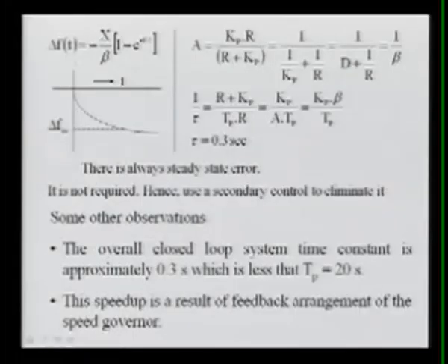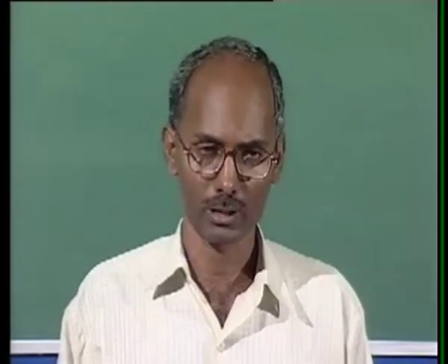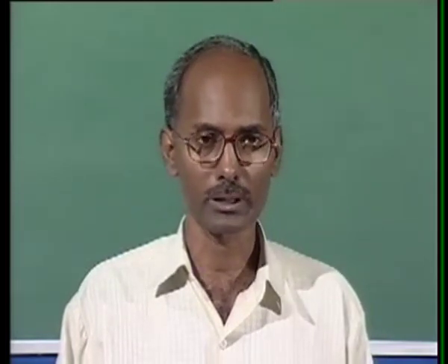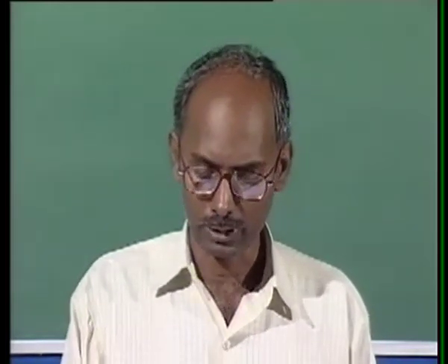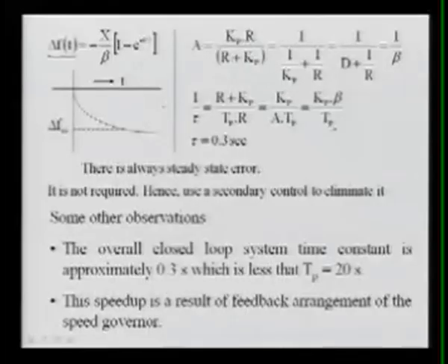So here I derived this expression of the frequency, that is, a time varying frequency. Here we ignored the time constant of the turbine and governing system, and took only the power system time constant, that is TP, and then we derived the simplified dynamic response. This x is the change in the load, the magnitude of how much you are changing it with the step that we are talking about. It is not a gradual change, it is a step change.